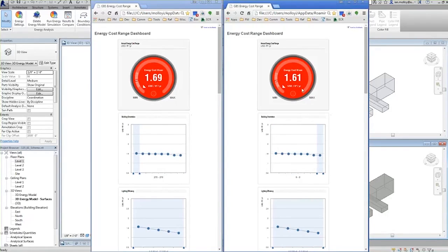Now, again, traditionally, people would get bogged down and say, well, is that 8 cents real? Because, you know, what are your other assumptions, garbage in, garbage out? What's really interesting here, if I just use lighting power density as an example, is that right now I'm using the entire range of lighting power density. If I was to say, well, let's say this is a very high-performing lighting system, I can see that for orientation, it's still an 8-cent difference. Or even if it was a very low-performing lighting system, you can see it's still an 8-cent difference.